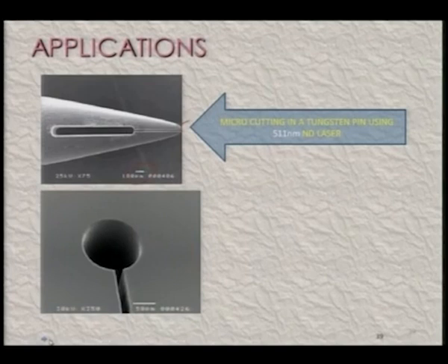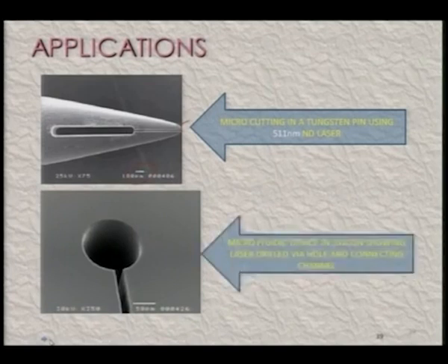Now, here is a hole which has been connected with the channel. So, you can see a microfluidic device in silicon showing a laser drilled hole and connecting channel. So, this has been done by laser beam, and this channel also has been cut with the help of the laser beam machining system, and both are connected and they are used as a microfluidic device. And the dimensions you can imagine, because this scale is given as 50 micron. So, definitely this channel width is around 15 to 20 micron, and this hole is larger, maybe 200 micron in size or so.